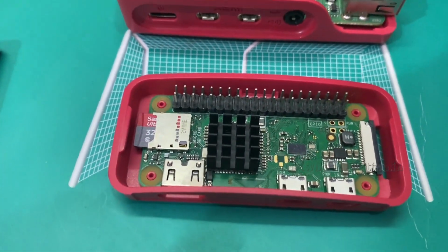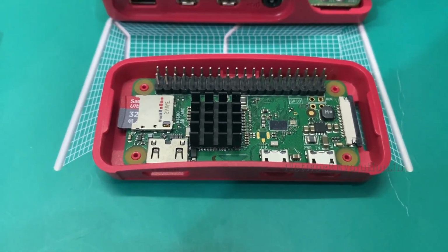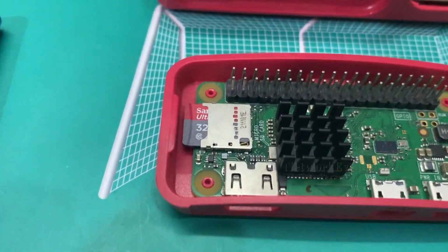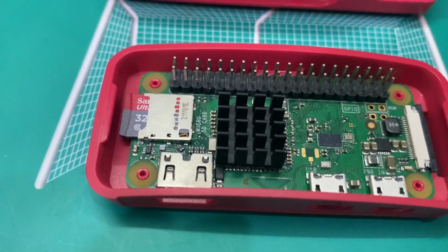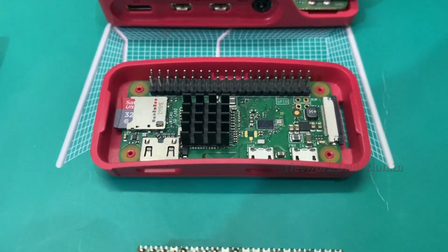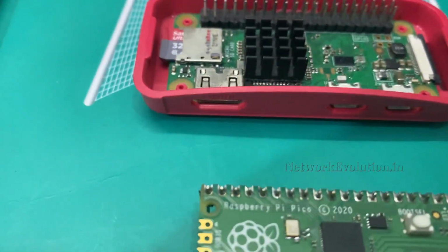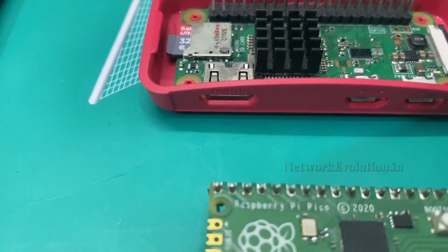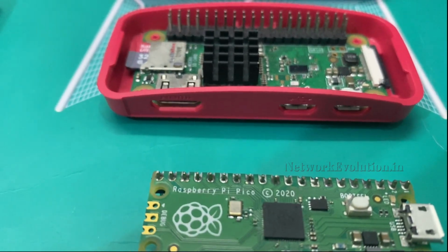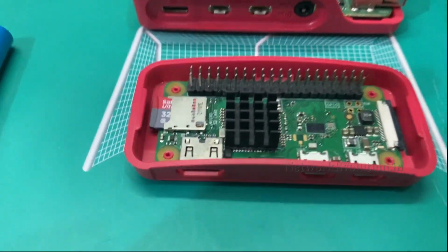And this is Raspberry Pi Zero W, and this is having processor with 1 gigahertz of clock speed and 512 MB of RAM, and this is even having a micro SD memory card slot. You can install operating system there. I have installed an OS there, and this even supports Wi-Fi and Bluetooth. Then here we have a mini HDMI port for display, and second port is micro USB port where you can extend to keyboard and mouse, and third port is power port.